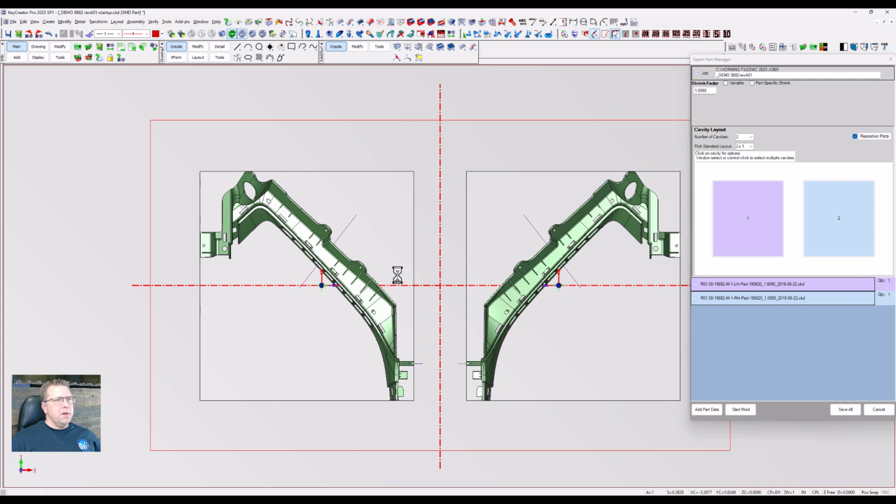So now what XPM has done is it's orientated the parts. We worked with it to establish the die draw. It's looking for one of the action lines, and it's making that action line square to the tool automatically. Often that's what we would strive for in tool making. In this case, we probably would want these larger actions square to the tool, so it'll just be a quick change.